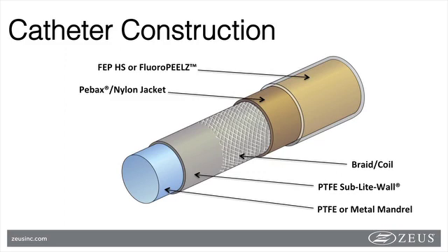Although the basic building blocks to construct a catheter are the same, working with soft durometer and small diameter materials has created its own inherent manufacturing challenges. When reflowing these more delicate underlying materials, or small diameter materials, it can be challenging to remove the FEP heat shrink without damaging the underlying material, causing yield loss and scrap. Due to these challenges, the industry has been asking for a peelable heat shrink, and not until 2014 has anyone been able to provide a solution.